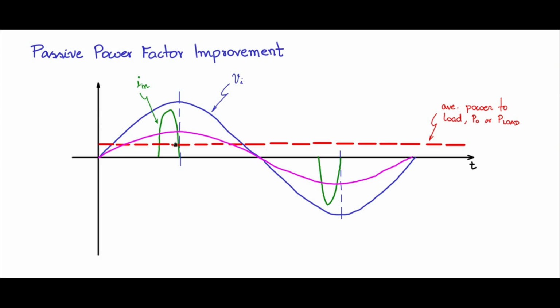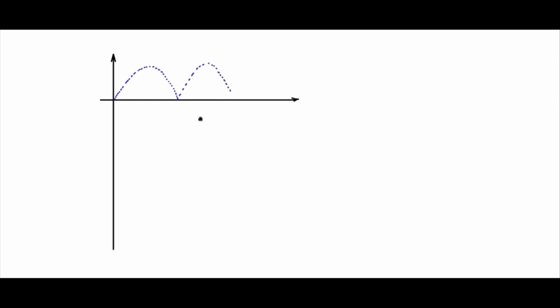The takeaway from here is that as I widen the base of conduction, the peak will start reducing. Now that is the takeaway that we are going to use for improving the power factor. To consolidate this, I am going to show three possibilities on the graph. Let me draw the rectified input source, and let me take the output voltage ripple in this fashion. Call this case 1.